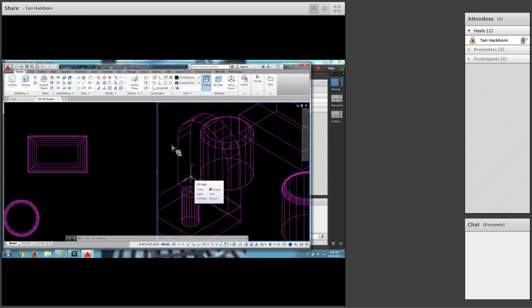And the cylinder has to go to the center back, so you're going to get near this back arc when you place it. Cylinder, get near the back arc. Okay, no, back arc. Ugh. Oh, brother. Everything's showing up except what I want to show up. The end point of the line is showing up. Oh. Is that it right there? I think it is. Okay, I'll do cylinder. I'll shift and right click and say center point. So that's the only thing that's going to show up is center points. Good. Okay, so I'm near the back arc and I can see the green center point. That's what I want to click on.